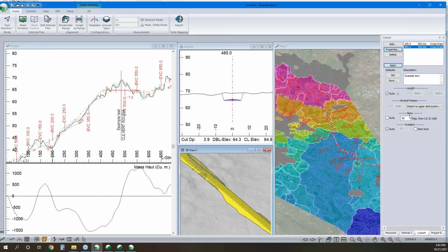If it was a matter of regrading or bringing in fill for that structure, so if your bridge had an excavation underneath of it that you wanted to bring up, then I would do that as a major culvert, and I would include the earthworks in the model and place it wherever you'd like. Hopefully that answers that. Excellent. And if we didn't, please type a follow-up in. We will absolutely address it.